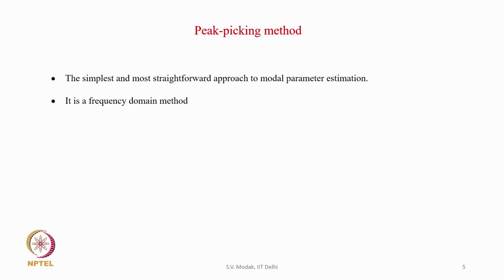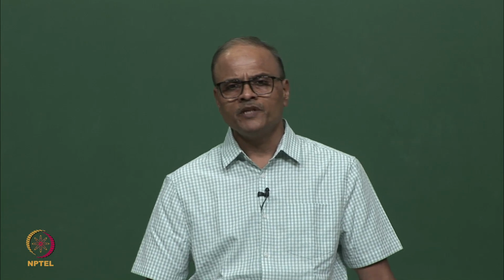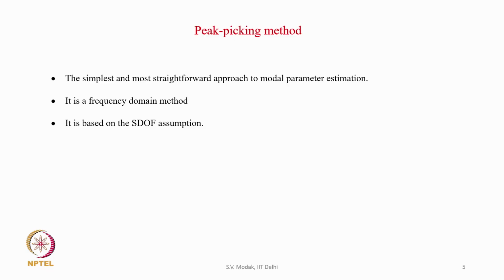So, it is a frequency domain method. It is going to fit the FRF expression to the measured FRF, and it is based on a single degree of freedom assumption. So, let us first of all look at what this single degree of freedom assumption is.